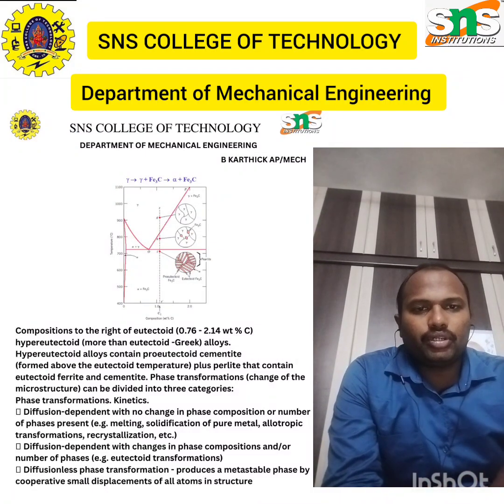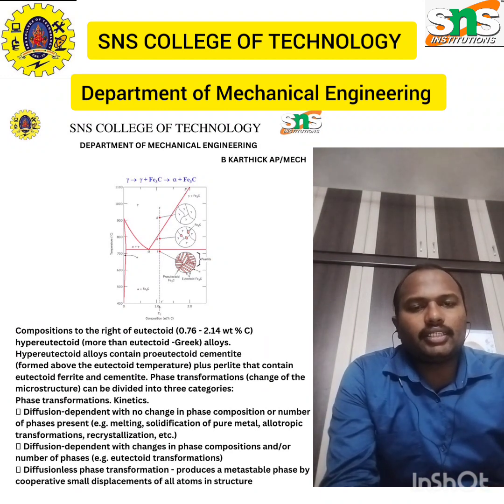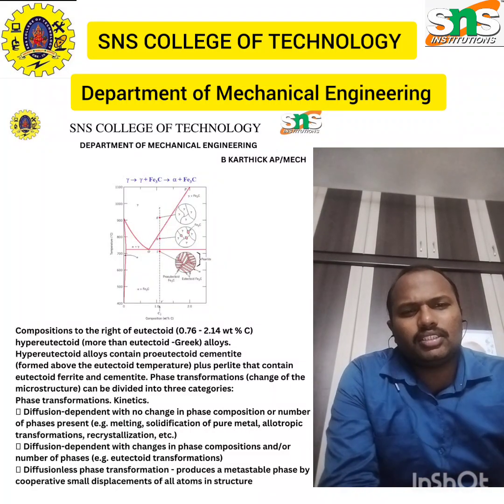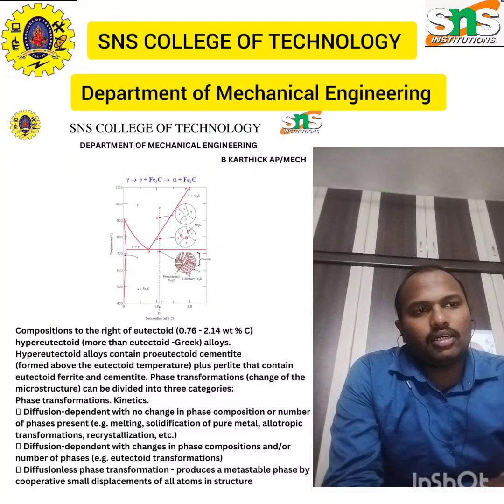But now we are going to see hypoeutectoid steel, where the steel formation occurs prior to the eutectoid reaction, or we can say the steel that occurs at less than 0.8% of carbon. So the main difference between eutectoid steel and hypoeutectoid steel is that you can see an extra alpha forming, which is known as proeutectoid alpha.